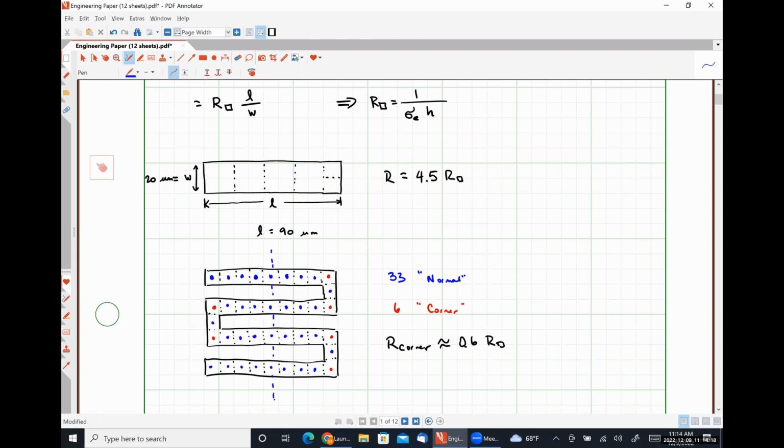So we'll see a larger relative change in the resistance, which is easier for us to measure. Okay, so that's why we would run a serpentine series of squares like this in a MEMS device. It makes that relative change in resistance, which is turned into an electrical signal by the piezo-resistive effect, into a larger and more easily observable signal. Okay, does that sound reasonable? All right.